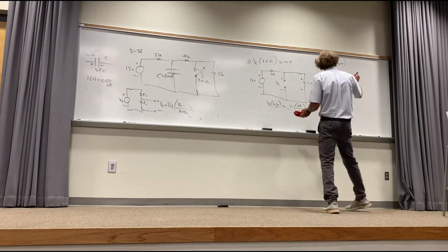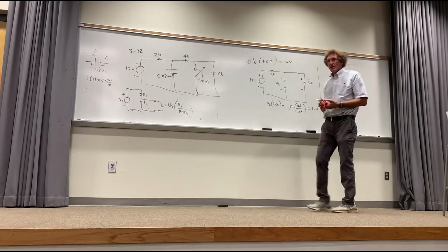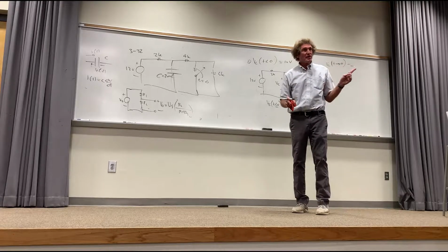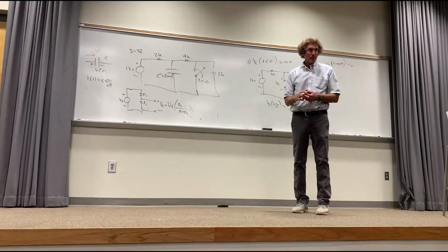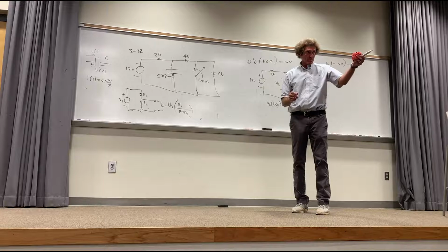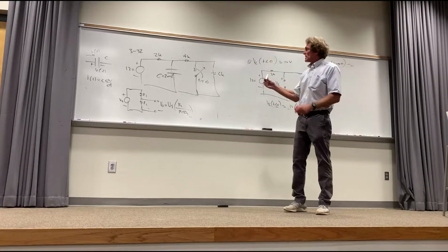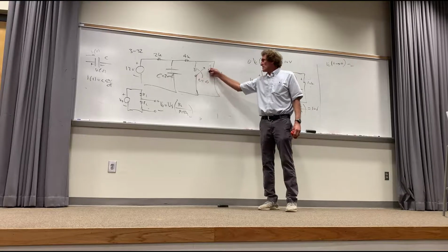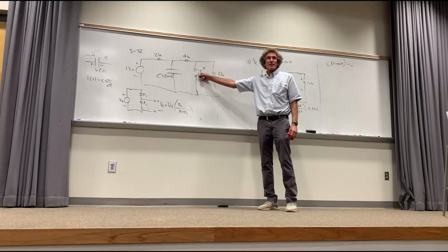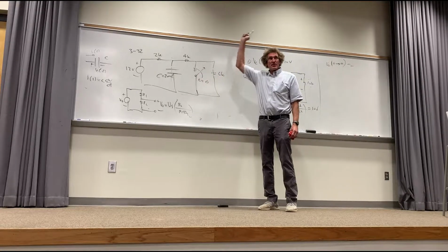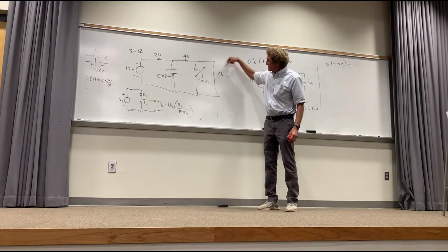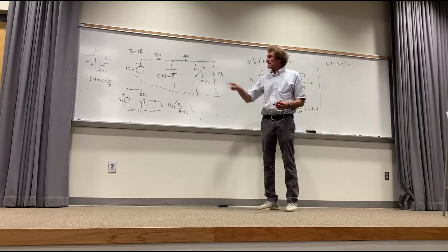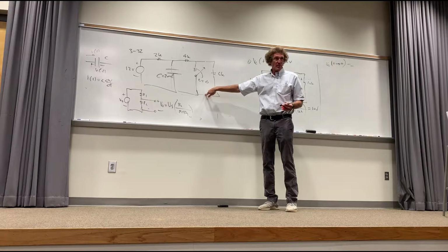So now what's the voltage as t goes to infinity? Well, when t goes to infinity, what's the next thing that happens? At t equals infinity, this switch is closed, right? If that's closed, how many see that 6K gets shorted out? You all see that? When that's closed, this 6K is not even a factor because that's a direct wire across there, right?